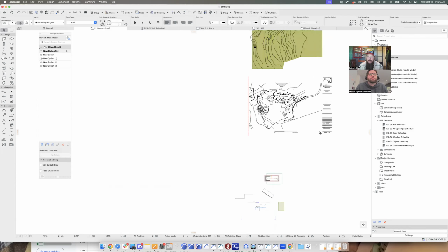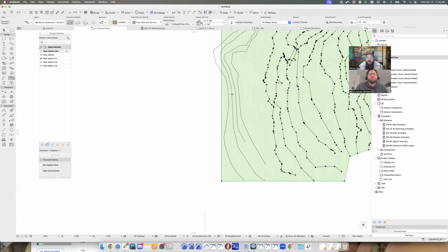That up there is my 280 contour. One thing that I usually do is, for the most part, not place these true to their elevation, because there are too many times where the elevations aren't just a couple hundred feet above sea level. They might be thousands of feet above sea level. And I don't want this site mesh to be, thinking about a project in Denver or Aspen, 4 or 5 thousand feet thick.